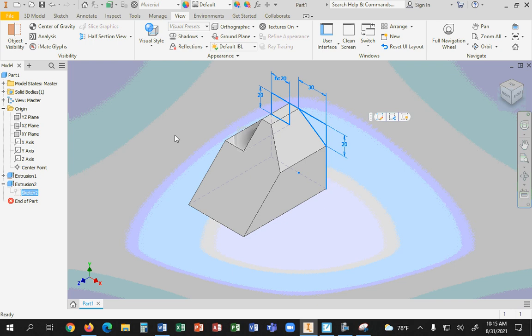They're going to insist that I need to have every single element independent of the other. And my answer to them is yes, you're correct. That is actually a very good habit to have. I agree. When you make your sketches, it is actually a good idea that every feature be independent of the other feature. Why? Because in the world of machining, for those of you that are sitting next to our CNCs, guess what? Every single cut requires a different tool, right? So I would agree with that individual complaining about the fact that I put two sketches in one cut. You're right.